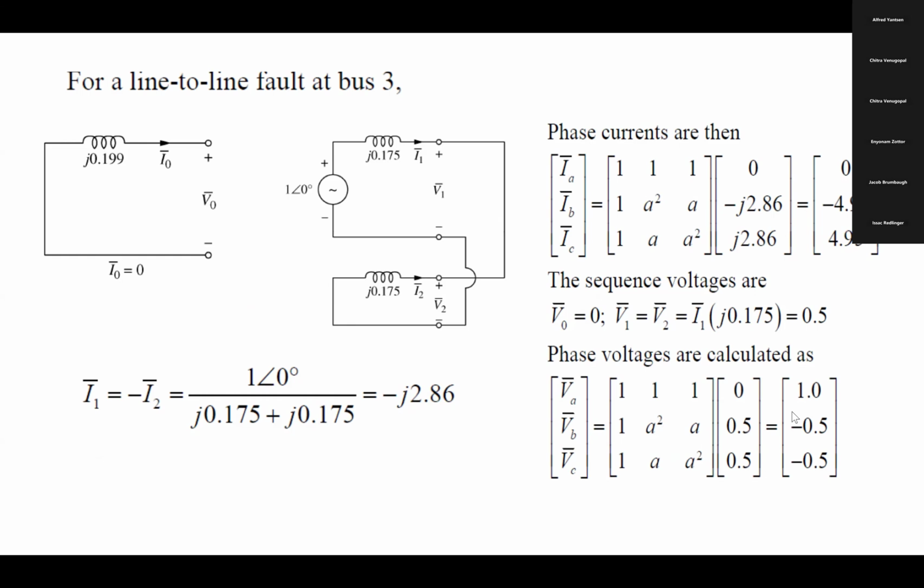Then only can you identify the actual fault value and the actual fault phases. Okay, you get the current, transfer it into ABC. Once you transfer it into ABC, you can clearly see that B is negative and C is positive. That shows it affected only B and C phases, not AB, not AC. Okay, because A is 0, which shows the perfect normal condition.